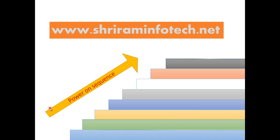Hi. Today we'll learn how the power sequence flows in any motherboard. These are the ladders where all the signals flow. First, when you connect the adapter to any laptop, the power that comes first is called the always voltage. It goes to the SIO and the PCH.